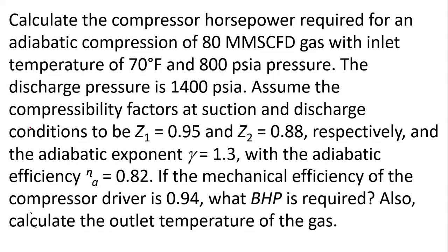Adiabatic exponent is equal to 1.3 with adiabatic efficiency of 0.8. If the mechanical efficiency of the compressor driver is 0.94, what is the brake horsepower required? Also calculate the outlet temperature of the gas.